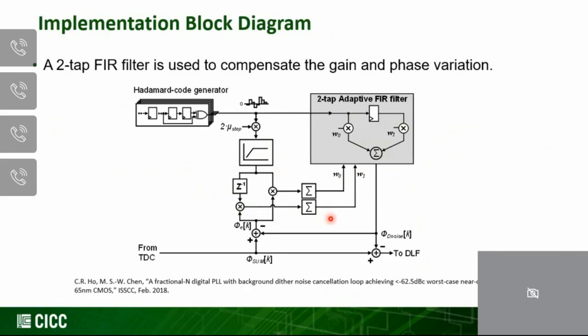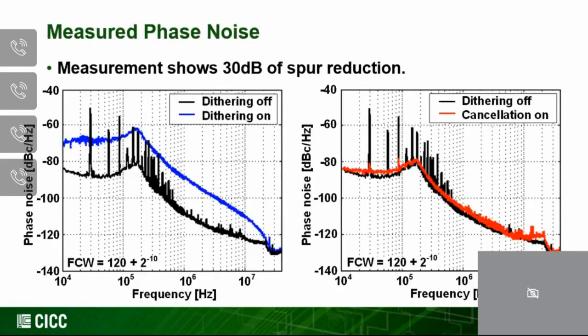So the bottom line here is that we just want to show you that all you need is just a 2-tap FIR, and it can already show a pretty decent approximation to the actual coupling path. So we can actually adjust the coefficient right here of this 2-tap FIR, and we can mimic to match the coupling path transfer function. So for more details, please go to this paper.